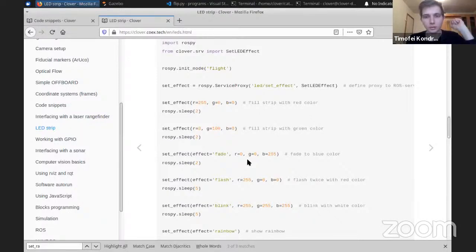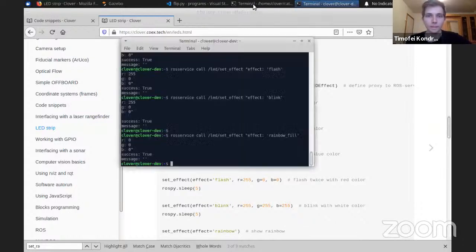You can have each one facing each direction. Well, this is not basically the API. This is more of the drone's setup, the ROS setup, how you arrange your sensors on your robot. So yes, you can have multiple rangefinders, and this is not going to be very difficult. You will just have multiple rangefinder topics in the topics list, and you can use each data in your code.